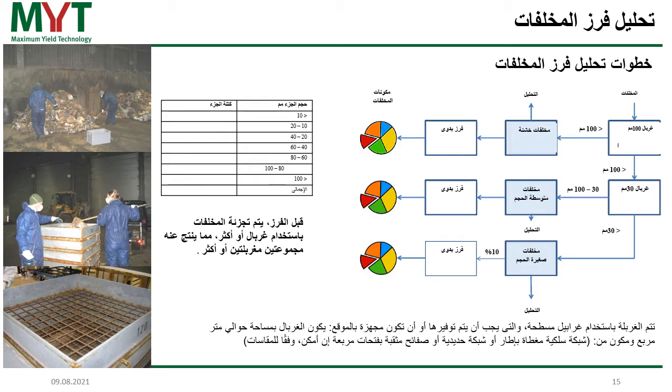You do not have to use 100 millimeters and 30 millimeters every time. You can set your diameters to the number you want. Sometimes 120 is a good size, or 80 millimeters is a good size. It also depends on how sophisticated you want to execute your waste sorting analysis. And of course, before the sorting, the waste is fractionated with 1 or more screen cuts, as I already told you, resulting in 2 or more screen fractions. So the screening is done before the sorting.